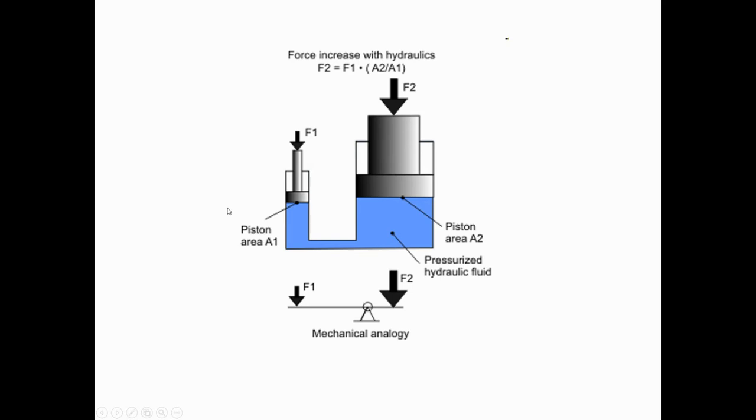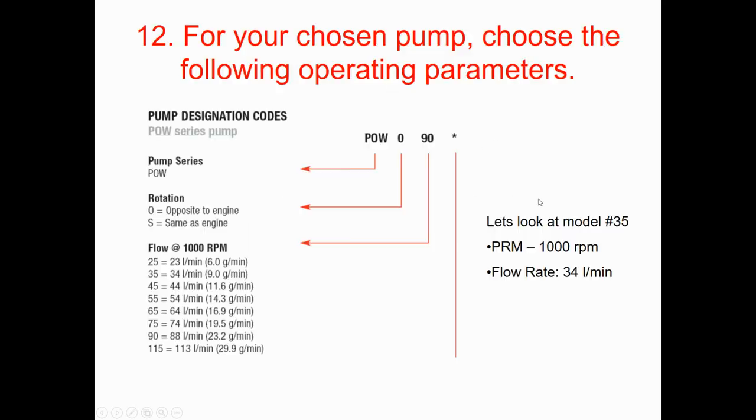That's what will happen inside the fluid. That's the magic of the fluid. So, for example, the same pressure is going to be distributed over this surface. If I multiply this pressure by this surface area, again, I find the value of force number 2. So what happened is I use a small force on a small area, and I achieve a larger force on the other side because the area of the piston has been increased.